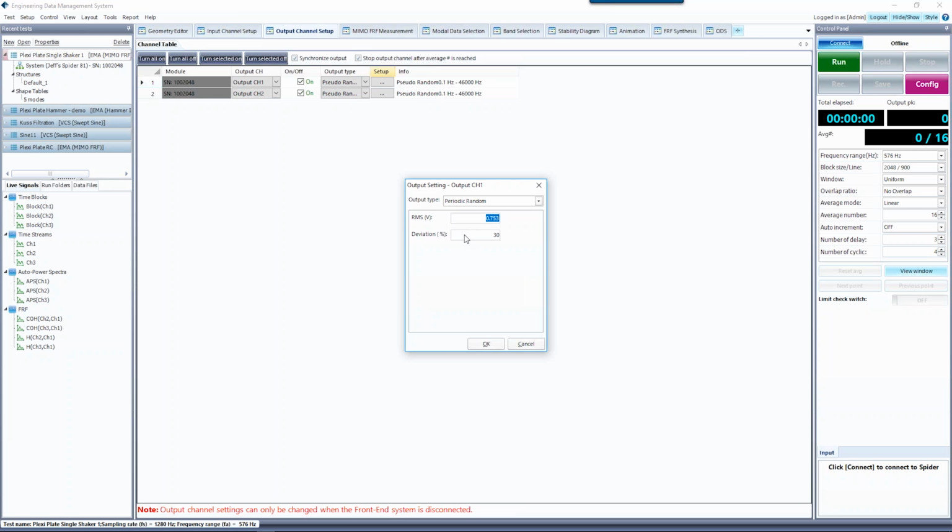So I can achieve much better, and in modal testing, people also always call it, because the structure always has some nonlinearity. But what's measured, the FRF, is called a linear estimation. So by using this theoretical random, changing also the level, not only the phase, you can get a much better linear estimation of the FRF. So that's the purpose.